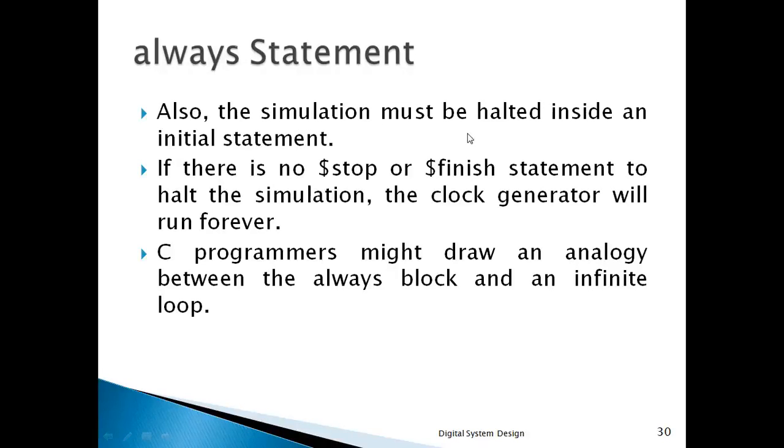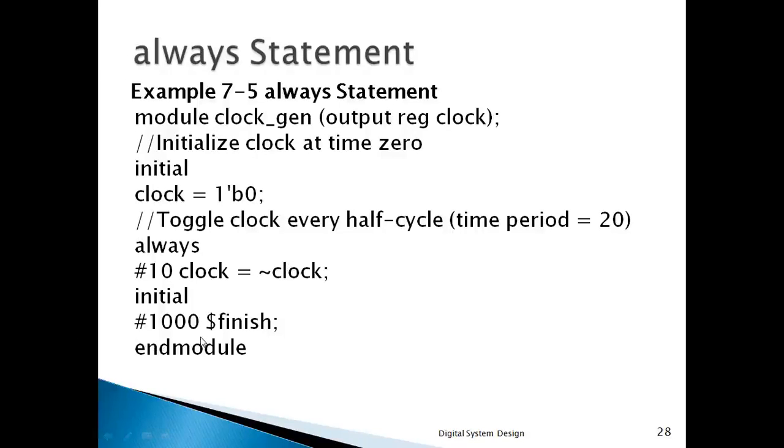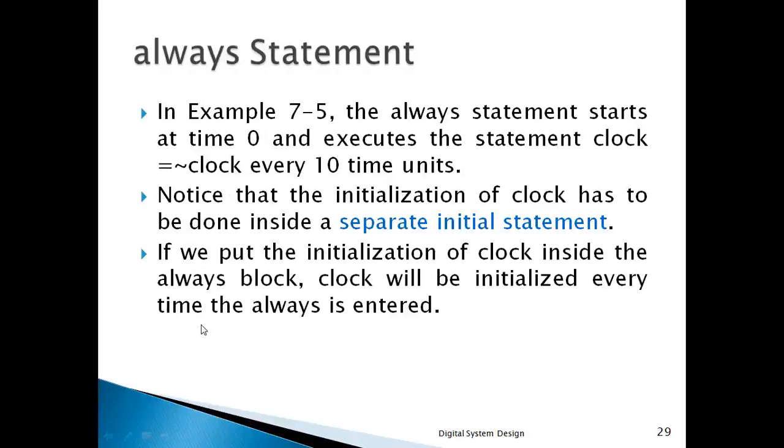Further, simulation must be halted inside an initial statement. If no stop or finish statement is given to halt the simulation, the clock generator will run forever. Here you see that this $finish statement is given in another initial block, and this always is separate from this statement.